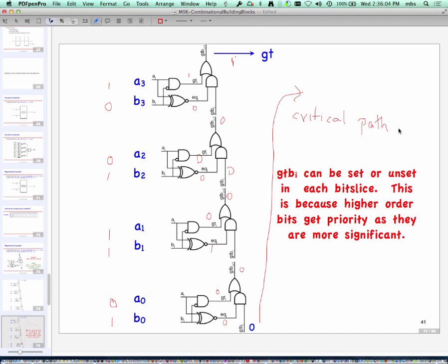What that means is in the worst case, my signal will have to start at one of these inputs, which are at bit position 0, and go through all that logic to generate the signal. Given the data pattern, I may have a shorter delay, but in the worst case, I may see something like that. So that's the disadvantage of this kind of logic where we are cascading across bits. Our arbiter was like this. It usually results in a more compact design, but usually a slower design. And that's the trade-off that one often has to make.